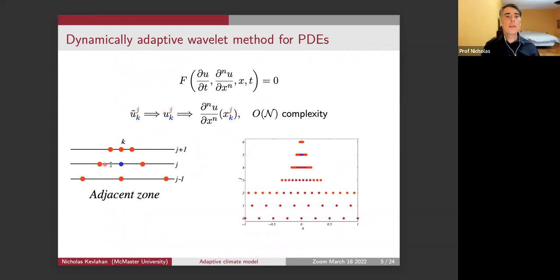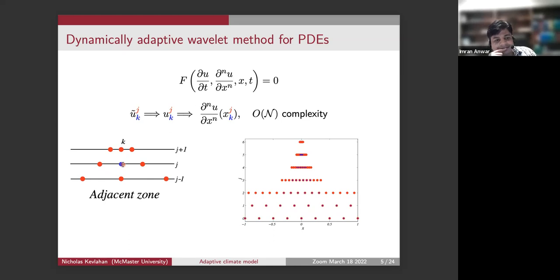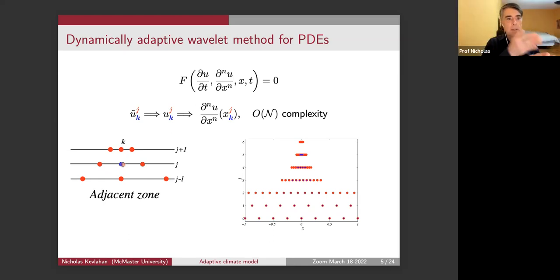No, all I'm saying is imagine you have an advection equation, okay? And you're solving it with a time stepping method. So you go from one time step to the next. Imagine also that you have a CFL criterion of 1. Okay, so that's a stability criterion. What that means is, in one time step, your front could move one grid point to the right, or maybe one grid point to the left.